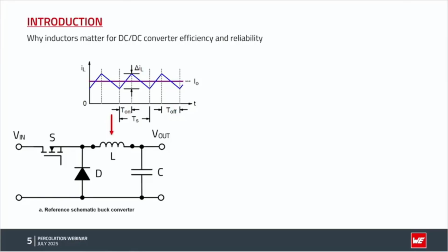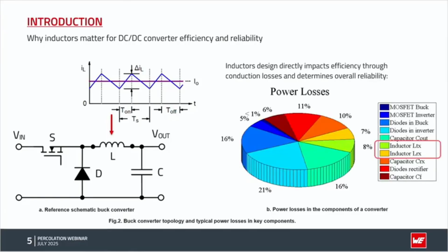Normally we have the losses already fixed, or we actually said that the inductor does not have a big role in the losses and the reliability over time. Why? Once you fix the design, we expect that the losses, as we can see in this picture, are not higher than 15%. Could be a little higher, could be a little lower, for sure it depends on which kind of inductor you are using and the design itself.